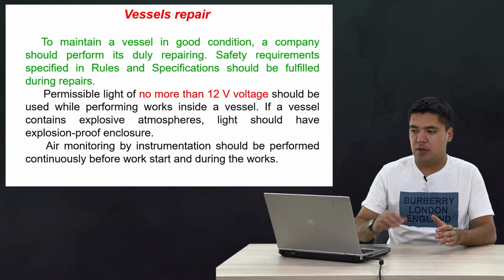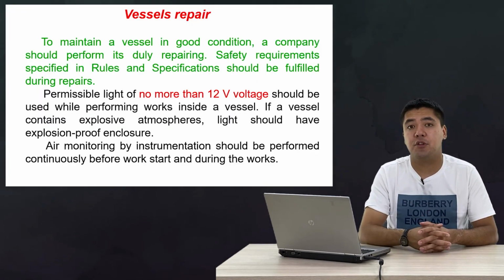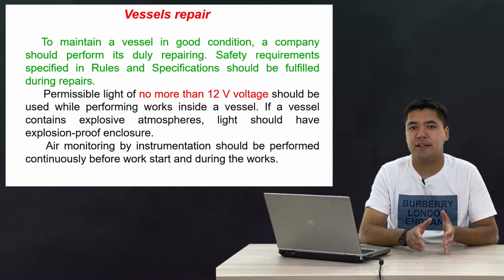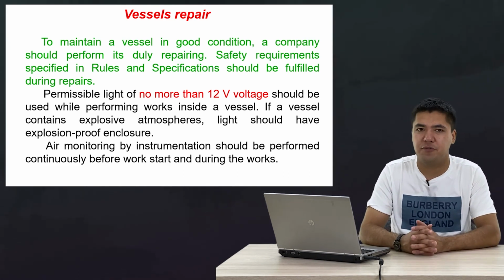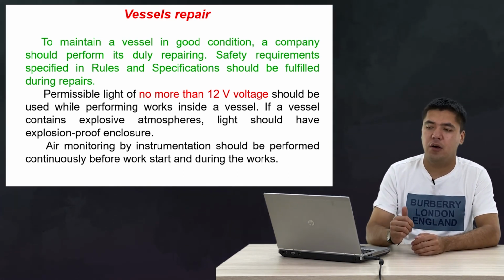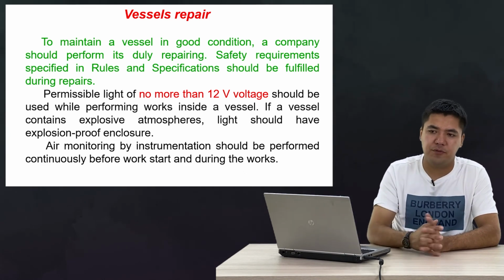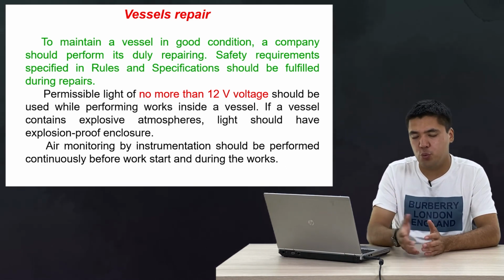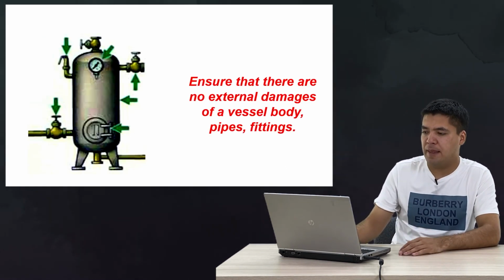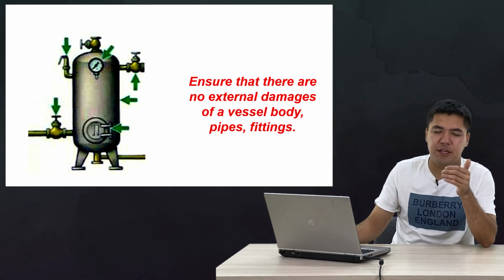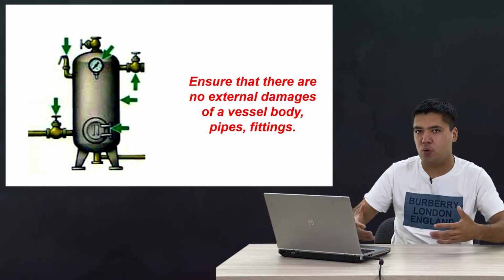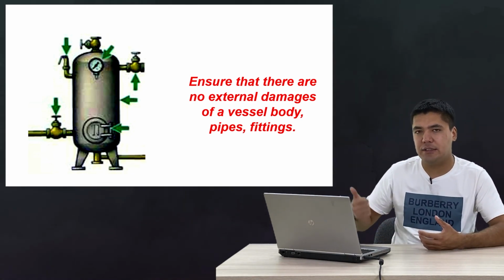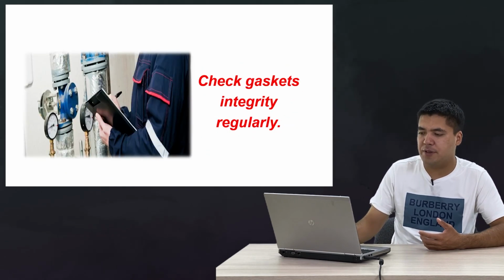construction activities. So we need to consider the pressure vessel as a confined space and do whatever is required for constructing or building a pressure vessel, like you need to use fire resistant clothing, for example, and intrinsically safe devices, for example. You need to open and work with a proper work permit, and you need to check the pressure level. If there is excess pressure, open the valve, release extra energy, and after all, you need to provide gas testing. Then you can allow entering the pressure vessels.